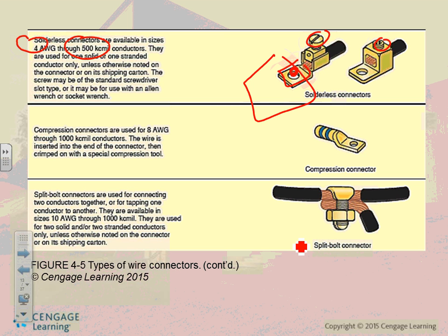This is how we typically tie to equipment, through a lug. A lot of equipment comes with a lug sitting on it. All you have to do is bring your cable and torque it. If it doesn't, then you put your lug here, and they have a hole where you can line the two holes together, put a bolt through them, and torque them. Okay. So this is your mechanical connector.